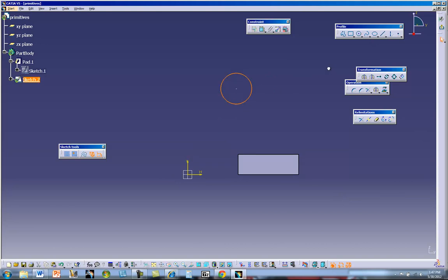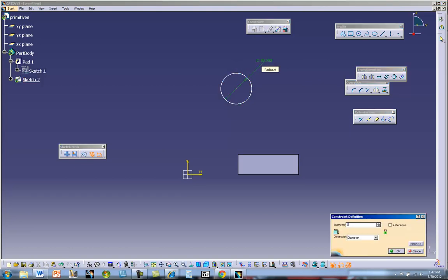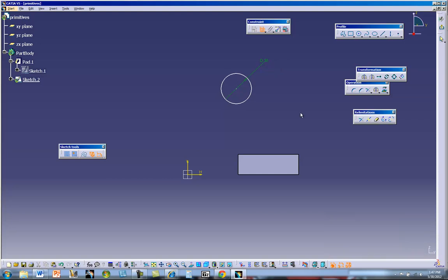And let's size the circle. So let's give it a value here. And let's change that to 30. And now we can locate this circle. We can say, well, let's go from maybe this plane right here, top of that to there. And now that location of this is controlling the location of the circle. So then maybe you want this side here to control it right there.